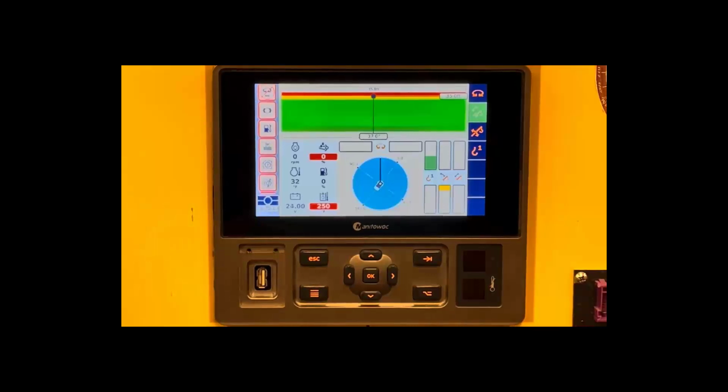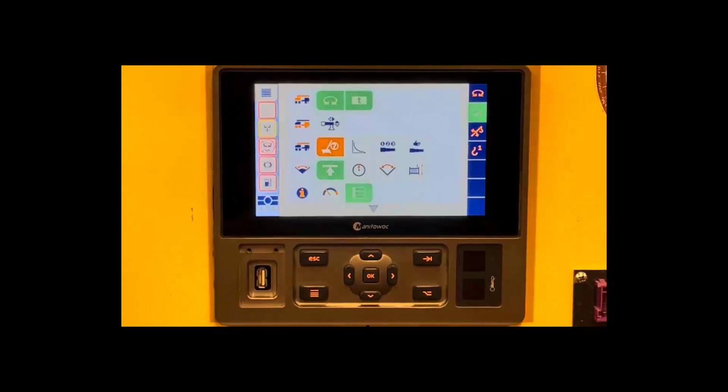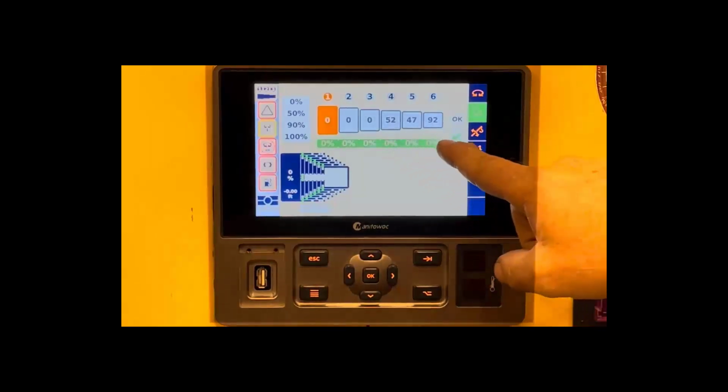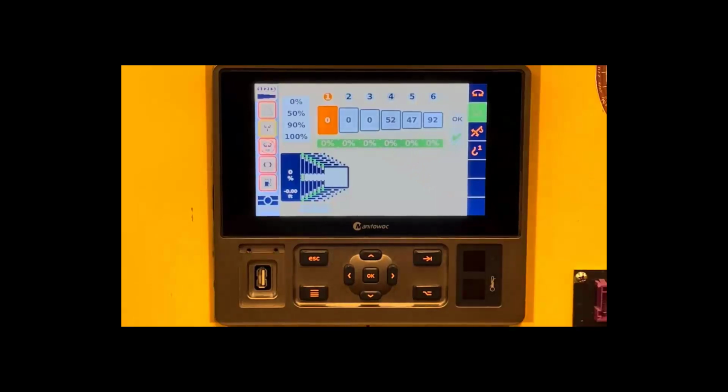So if we want to view the telescoping of the boom, we can view those percentages on the RCL screen, or we can select menu, go to the semi-automatic mode, select the semi-automatic mode. Here we see our configuration setup and that we are ready to telescope. Telescope icon is on, and now we could start telescoping the boom to those set values to achieve our length, radius, and load capacity that we selected through the boom configurator.